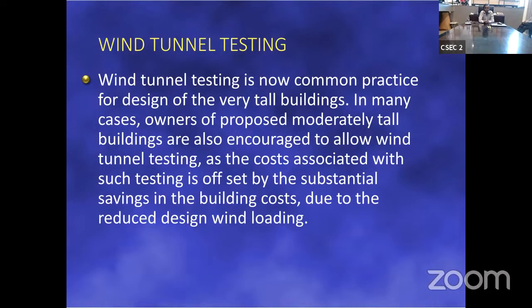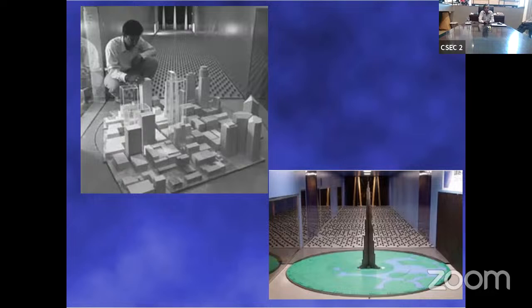some of the papers. Wind tunnel testing, very quickly. We need to do the wind tunnel test really to get it right. We rotate the wind tunnel, look at the wind speeds from different sides, and then calculate the loads. That's the Burj Khalifa on the right-hand side. Why we don't need a full city? Because it's so tall, we don't need to model the full city.